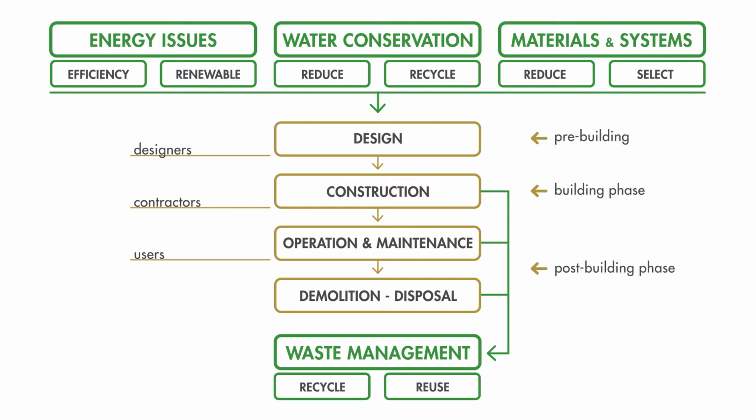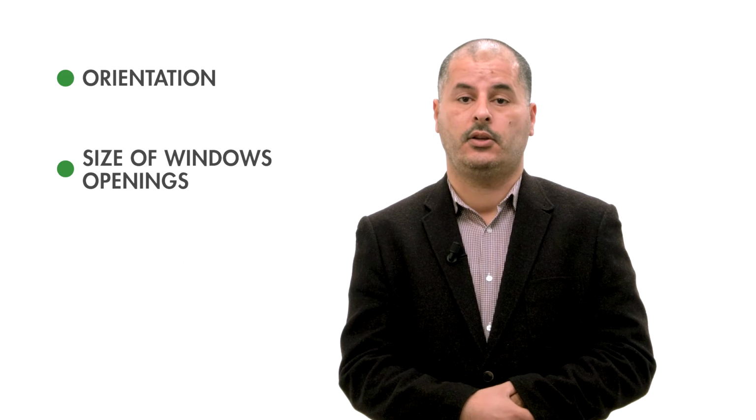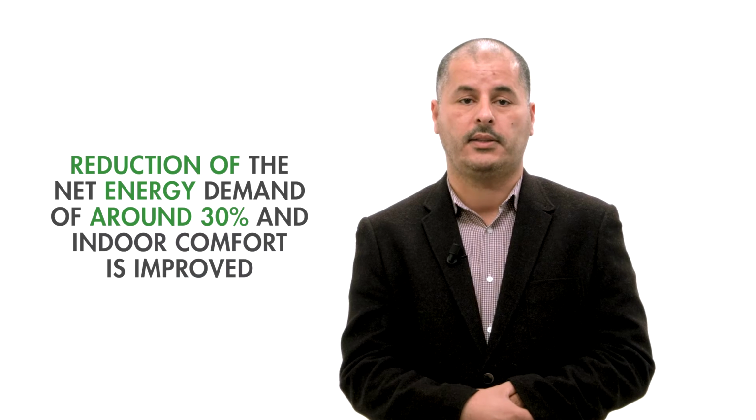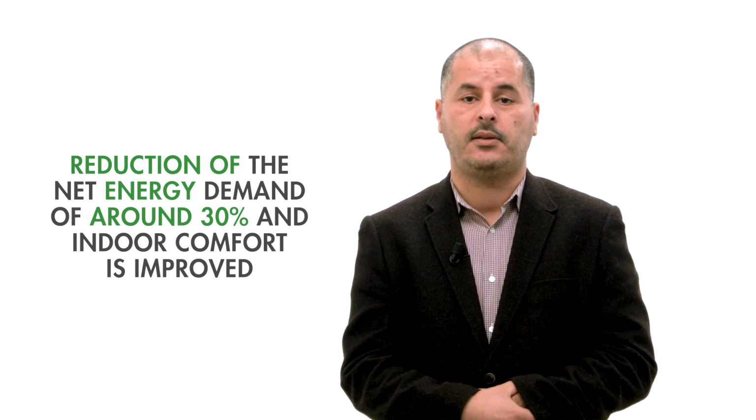Sustainable construction approach usually starts from the architectural design at the preliminary sketches and understanding the main strategies. Simple strategies such as orientation, size of window openings, shading, and insulation easily lead to a reduction of the net energy demand of around 30%. And at the same time, indoor comfort is improved.